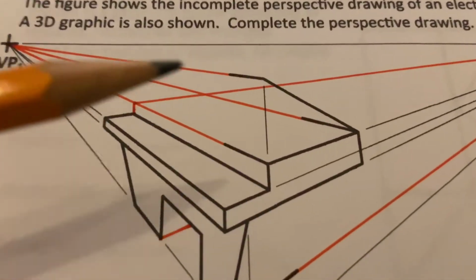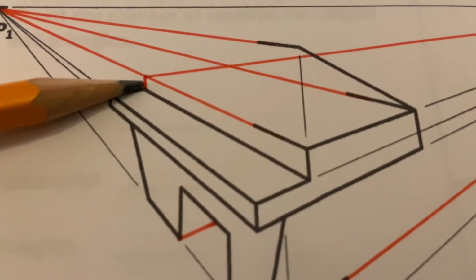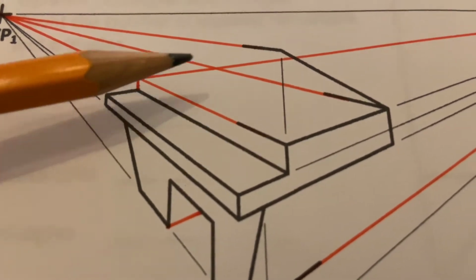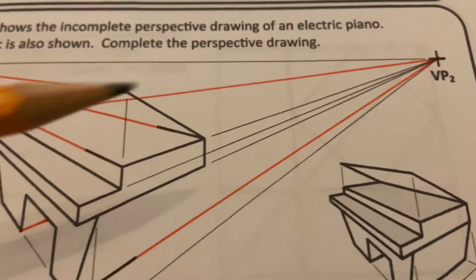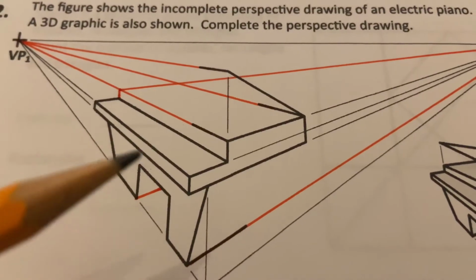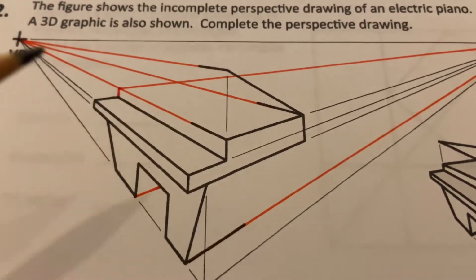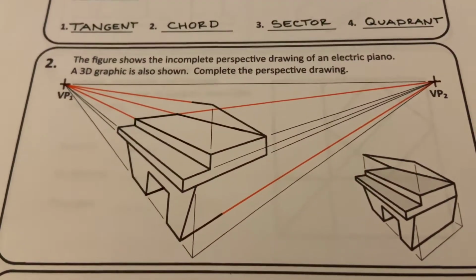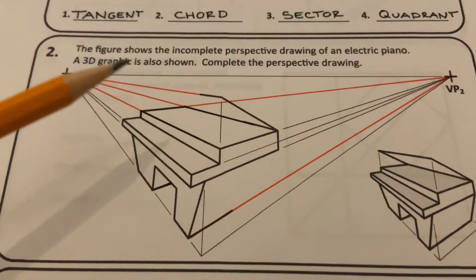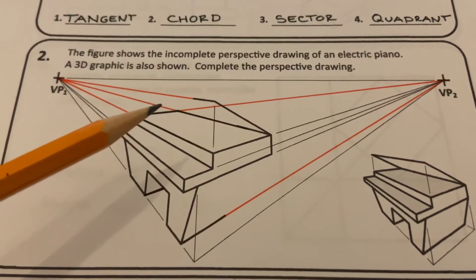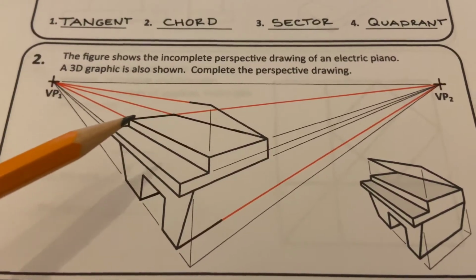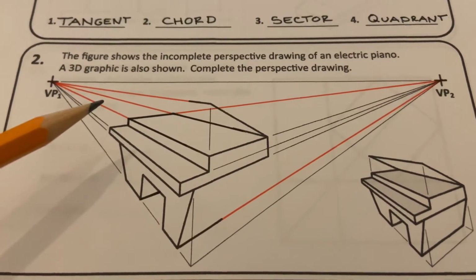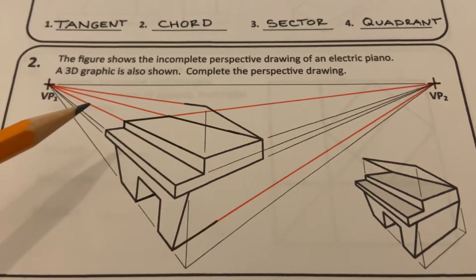In relation to this line here, you have to first of all draw a small vertical line and then bring that back over to VP2. And then all of these other lines here go and converge on VP1. Now, what I should have mentioned in the first part of the explanation is, although I have these lines here indicated in colour, when you're drawing them onto the sheet here, put them in very, very light pencil.